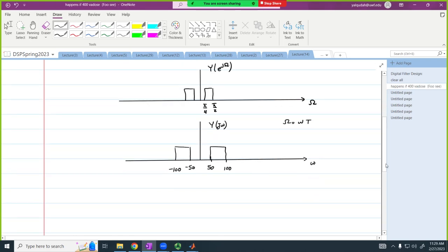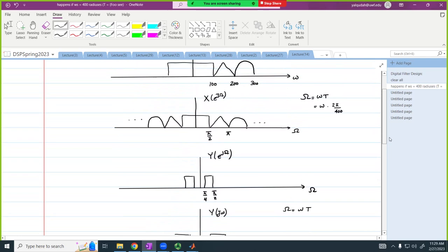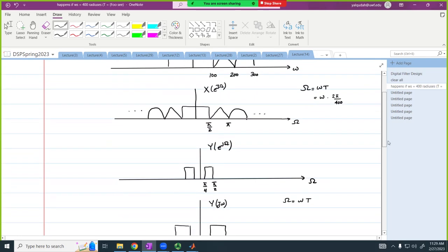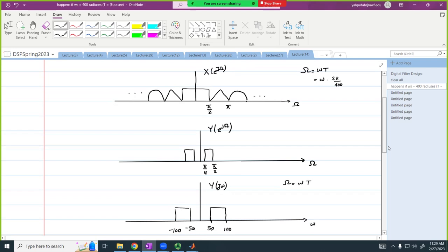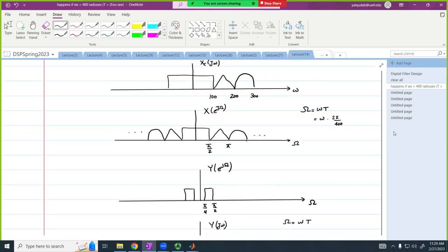Don't you have noise because you didn't sample at the right Nyquist criteria? Like, if you're not sampling fast enough, the highest frequency is 300 here, right? The sampling frequency is 400. Sure. So that means 200. Yes, I mean, there might also be aliasing that is caused by these elements. A very good point. Excellent point.